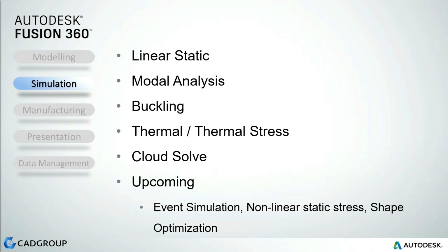Now, as of today, there are several new studies available in Fusion 360 as fully functional previews, and we're hoping to see these in full production mode in the next few months. But right now, they're fully functional previews. We've got event simulation, which allows you to investigate the effect of multi-body interactions in your components. So, for example, when you're creating a plastic fitting and doing some snap fits for that fitting, what does that actually look like in terms of the motion and the stress? Stuff like drop tests, you can simulate with event simulation.